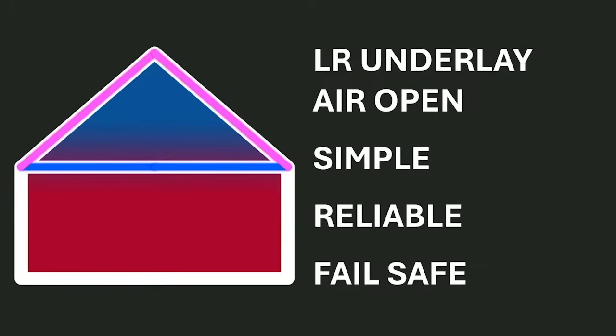Given the various categories and differing guidance for ventilation, and the lack of clear specification advice for more complex roof types and shapes, a similar option is often to omit the ventilation altogether and rely instead on the vapour permeability of the underlay to remove moisture.